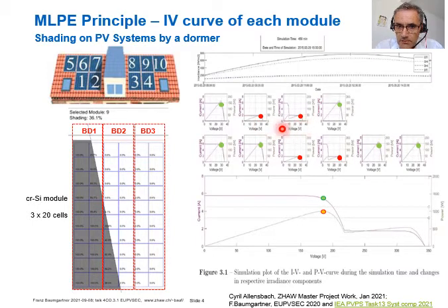The red dots mean the optimum power is reached at smaller output currents of 2 amps. So the optimizers have the option to operate these 4 modules at 2 amps, and the other optimizers operate the other, unshaded modules at higher amps.